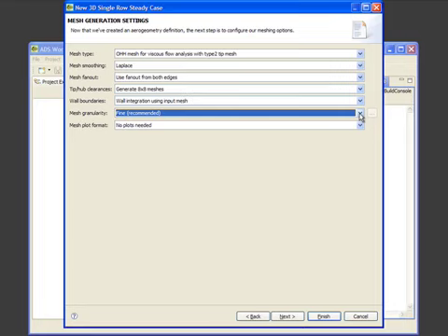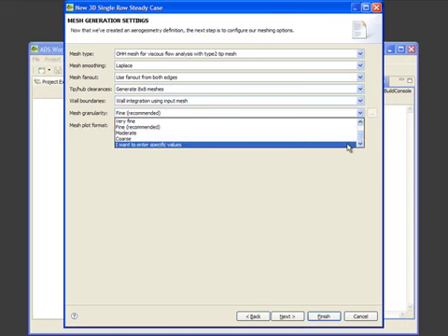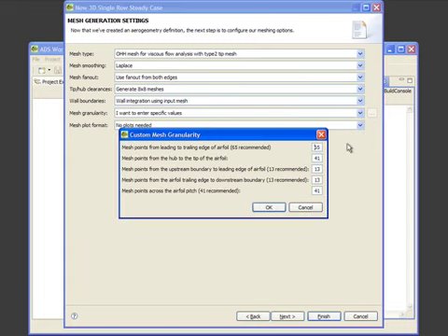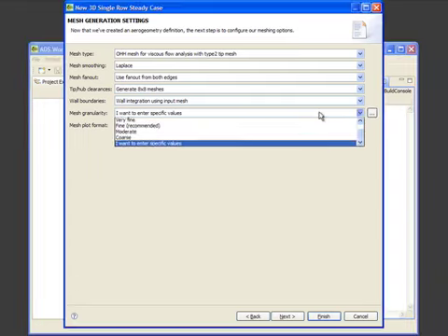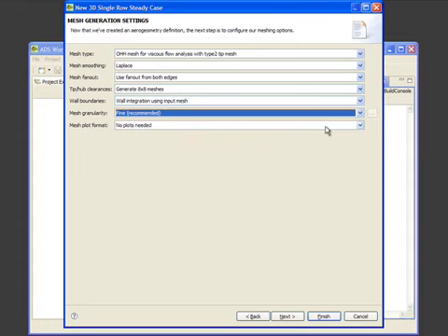There are recommended granularities that the ADS tool suite already comes with, ranging from very fine to coarse. If you, however, need more customization, you have the ability to select and enter your own values. ADS recommends using fine. It is a good combination, like the other two, of speed and accuracy.